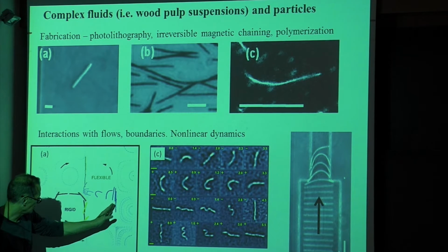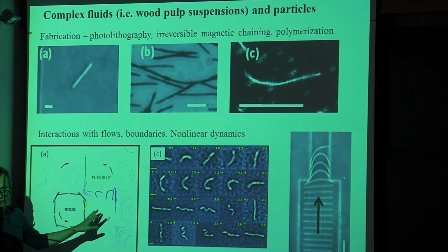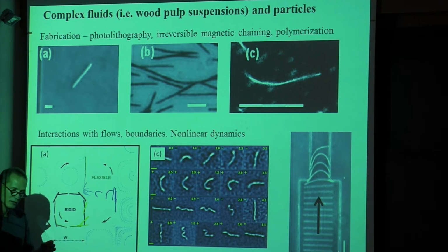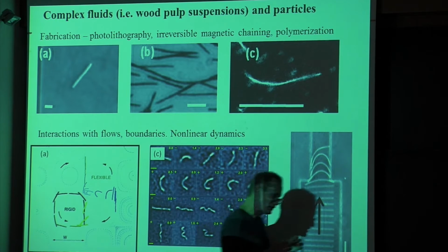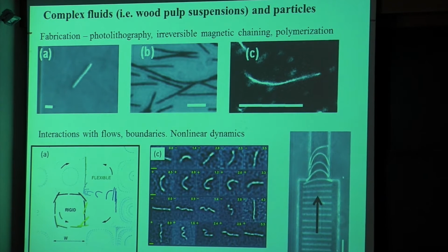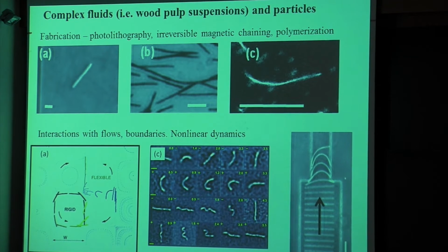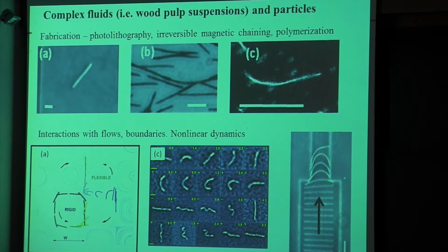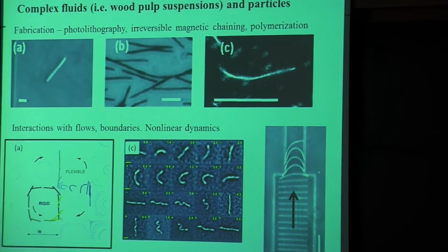And so here it's kind of moving along. It hits a stagnation point, and I'll talk about this problem later. It hits a stagnation point, and you have to ask, where do the stresses come from that cause something interesting to happen? In these types of systems, when you think about having elastica, the classical problem is that you imagine that the elastica is end-loaded, right? And so you have an elastica, and you have forces on the end, and you're pushing it, and then you're looking for a bifurcation to a buckled state.